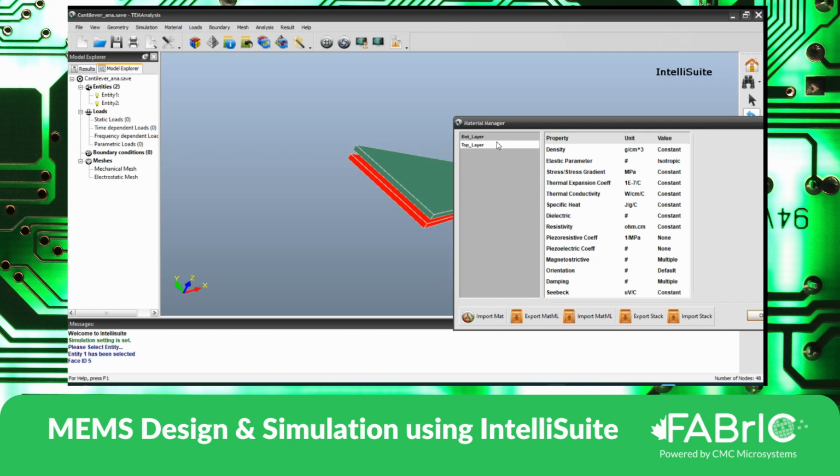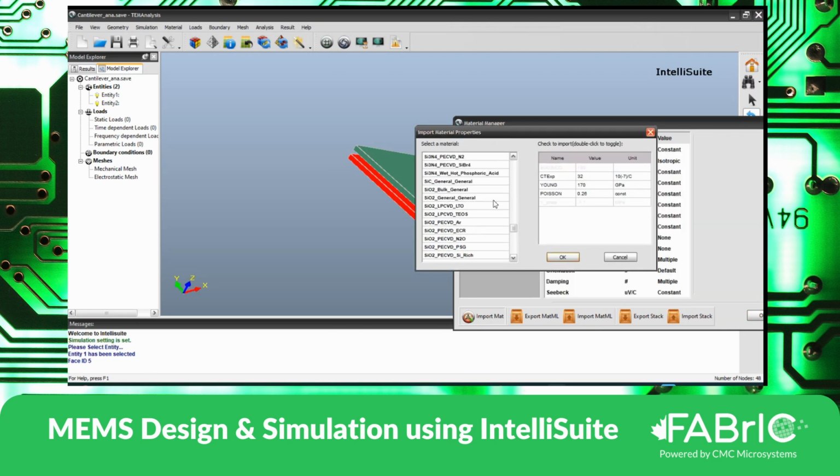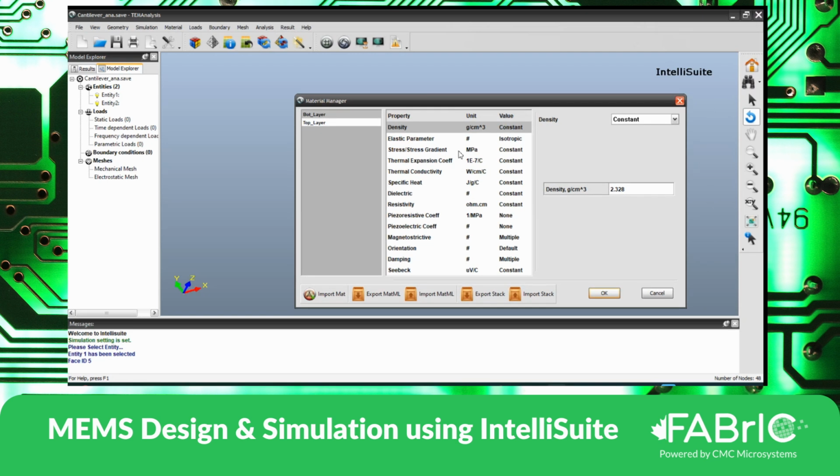So the bottom layer, the one which is turned red, import. I can select any material that I wish to. By default, everything is considered polysilicon unless we want to define something different. So let me take silicon 100, and these are all the material properties that we have with Si100. Now I go back and verify one by one.